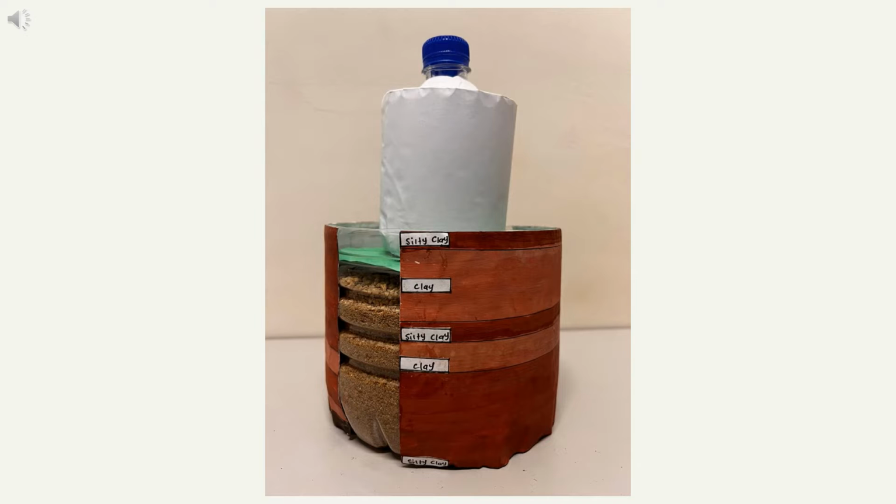So basically, the borehole water comes from rain and rivers leaking through layers of rock from the underground area. Water layers of rock or clay separate and restrict underground water bodies at different depths in different areas. These areas are called aquifers. A rock aquifer can have its aquifer yield boosted by natural cracking. Groundwater is stored and transported in solid and naturally occurring breakage within the rock. Boreholes are drilled into a network of cracks that yield water.